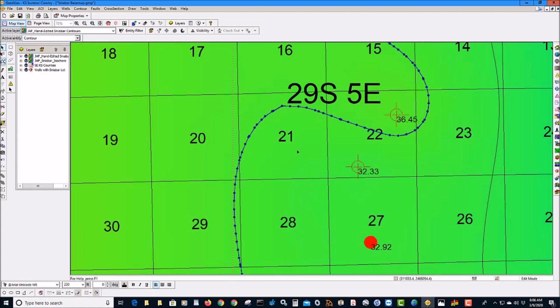It's a compromise in terms of the accuracy of the map in areas where you have a lot of tight data, but you can do that iteratively and figure out the best setting, because again, the larger the smallest feature radius, i.e. the less detailed your grid, the fewer nodes you'll have on your contour line. So there's going to be some happy medium that will allow you to effectively edit your contours without having to delete hundreds of nodes. But again, we're working on a solution for that.